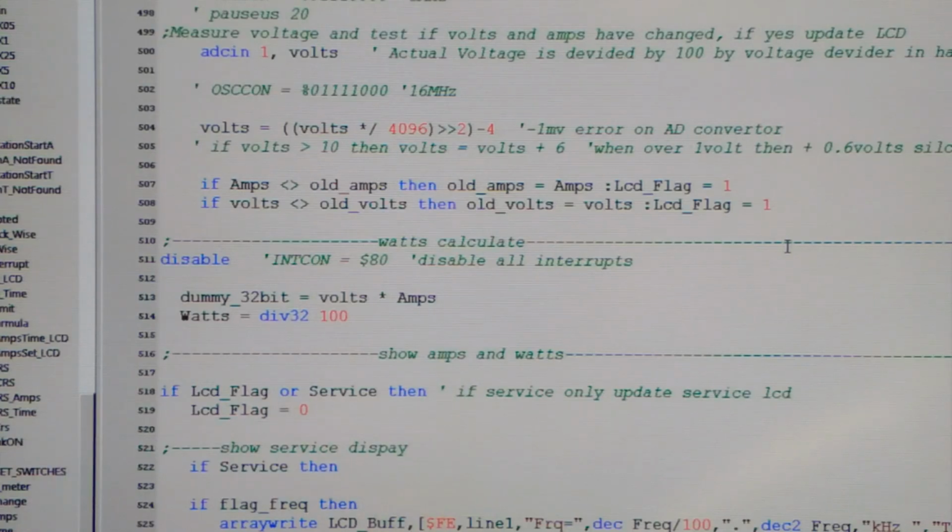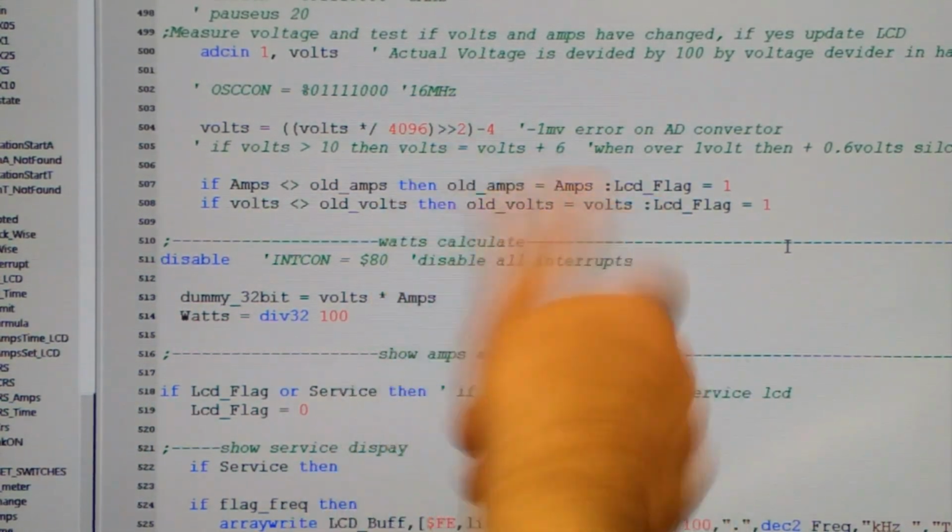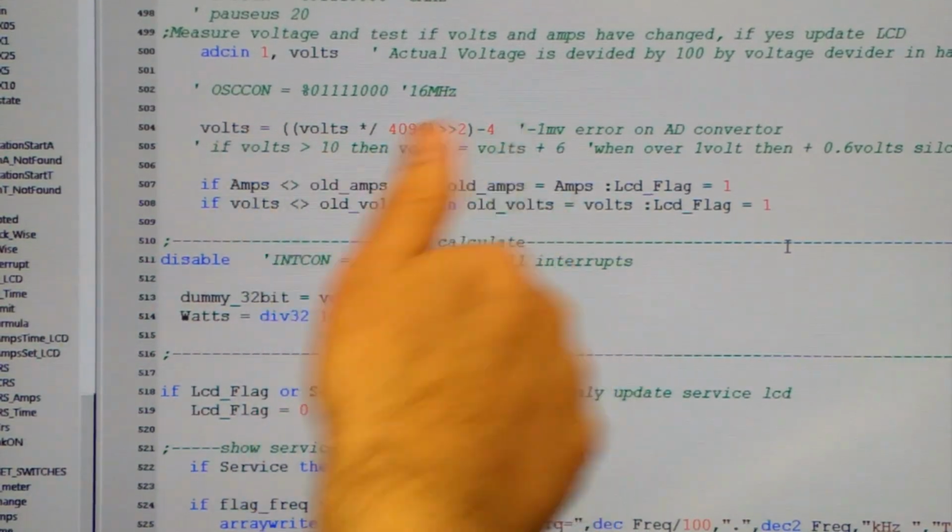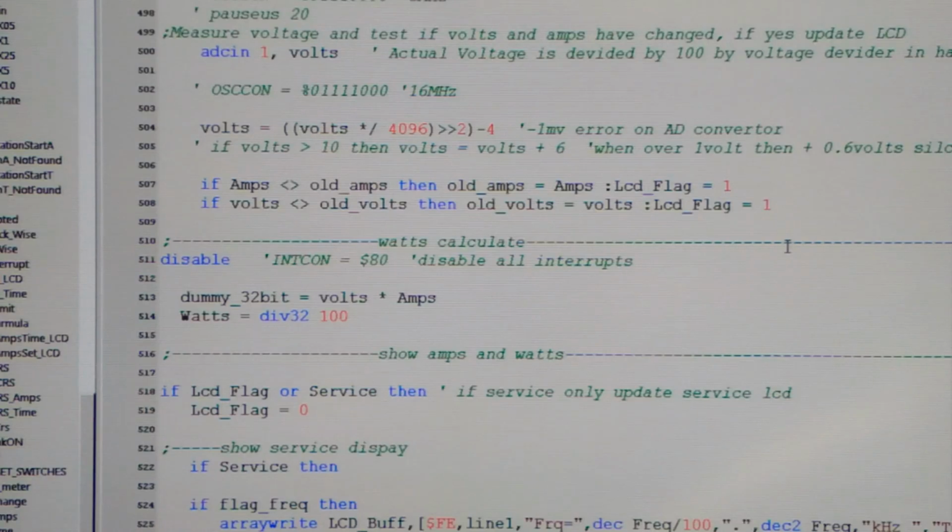Because every time you do a write, first of all, in most codes, if you're using interrupts, you have to switch off the interrupt. That means you're delaying your interrupt, because if you happen to turn your rotary encoder, which means it should jump to an interrupt, because I'm writing to the screen, it cannot go to the interrupt. You can make it go to the interrupt, but then get prepared for your LCD screen to display some error, because you never let the communication finish.